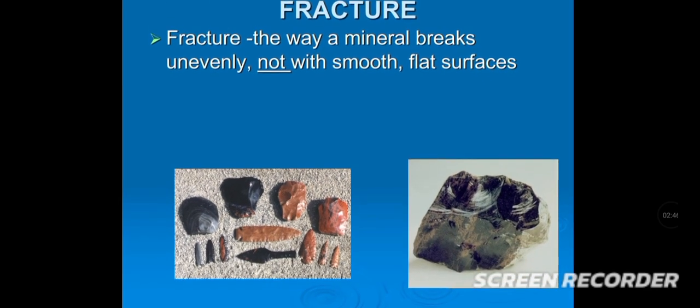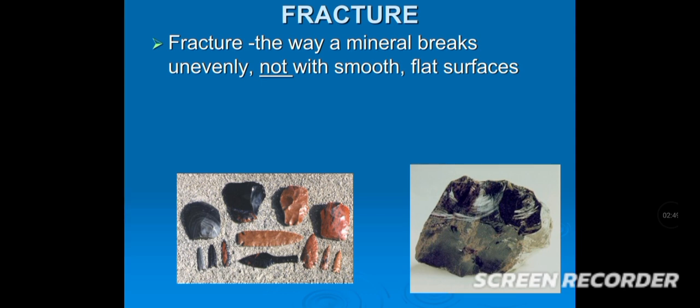So, as a civil engineer, why will we study fracture? As I have discussed earlier also, civil engineers should know where a building or any kind of construction can be conducted. If we don't know the weaker planes or the fracture planes of a mineral or of a rock, then it will be a big blunder, because without knowing properly the cleavage or fracture planes, if we construct anything on a weaker plane of a rock or a mineral, then the construction can collapse very easily. So that's why the study of fracture is also very important.